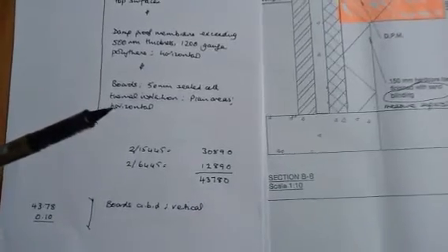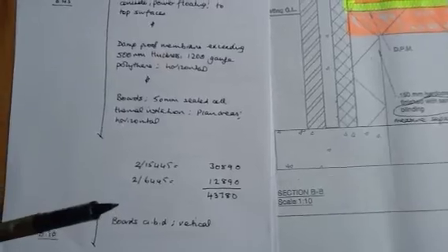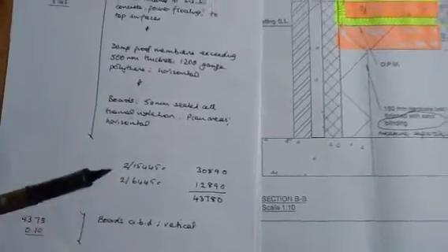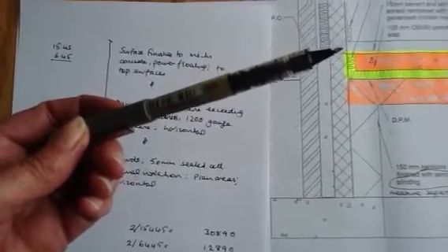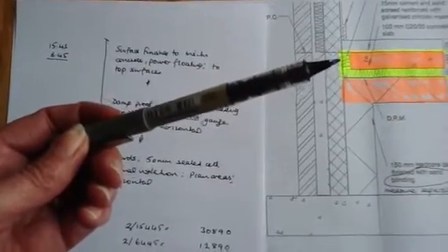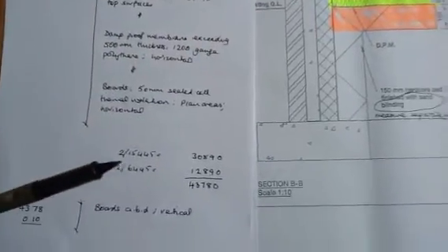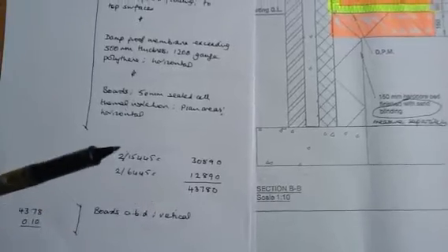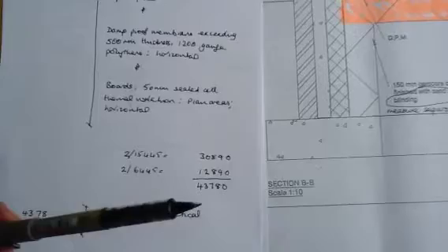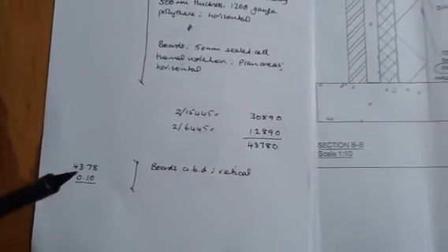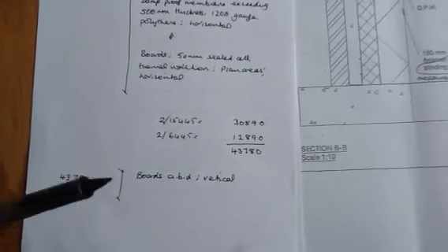In terms of the vertical board, what I want is to measure the area, so it's going to be the internal perimeter, i.e. the internal girth based on the inside of the blockwork. You've actually already got that, but I've recalculated it here by twice the internal length plus twice the internal width, and then multiplied it by the height of the concrete slab to give me my area of vertical board.